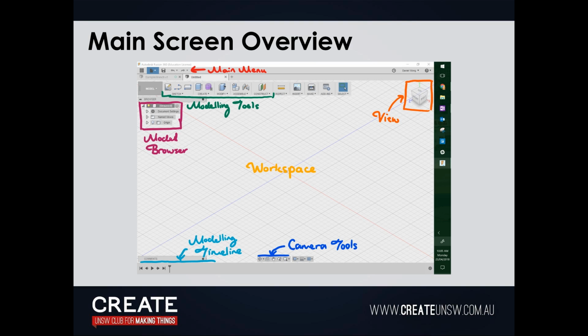Viewports, so you can have four windows showing different angles of your CAD. Won't go into that today. Having a mouse is much more convenient for this. So with the mouse, usually the right click button is the orbit. We can't see anything right now because there's nothing to see, right? If you right click and drag, it'll show you functions. If you hold shift and the middle mouse button, you'll drag around.